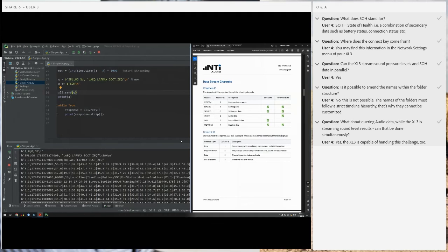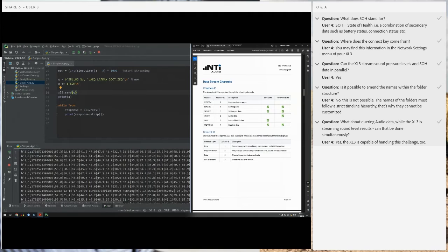The content ID, first of all, the device responded with a header. We call this begin of stream, which is a 2. We see here the 2 and here the 2, which is the header, and then the data, which is 3. There are situations, if I now would press stop on the device, where the device no longer has data, and then it will respond with a 4, end of stream. We will see this later, or just now when we are trying to get audio from the device, we will also see a 4 then.